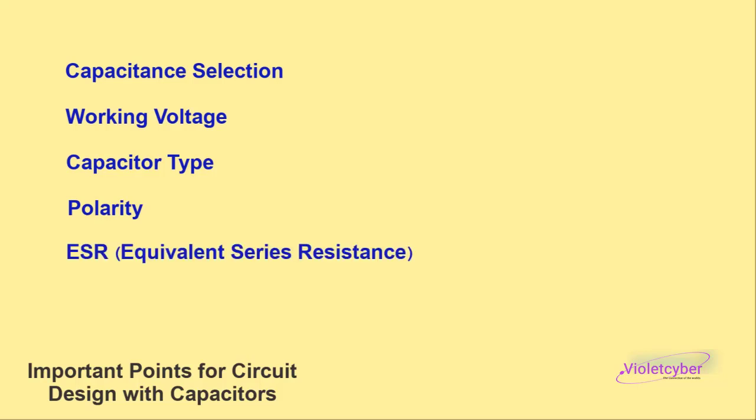Next one, ESR or equivalent series resistance. ESR impacts the performance of capacitors, especially at high frequencies. Capacitors with low ESR are better for power filters and switching circuits. Pay attention. Tip: in switching power supply circuits, choose capacitors with low ESR to minimize voltage ripple.